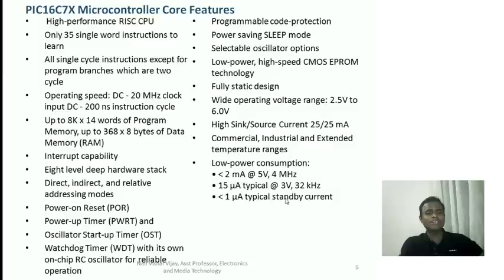Each pin on your big microcontroller can bear a load of up to 25 milliampere. And it has commercial and industrial extended temperature ranges, which makes it feasible or flexible to be used either in commercial or industrial sectors. It has a very low power consumption compared to many microcontrollers out there. It is less than 2 milliampere at 5 volt and less than up to 15 microamperes at 3 volt. So that is a very low power consumption comparatively.